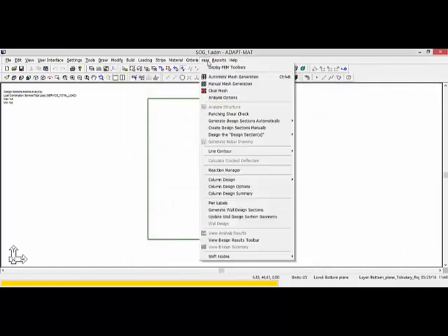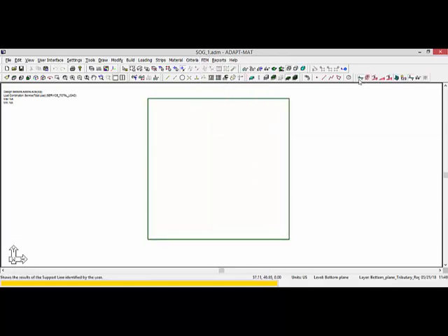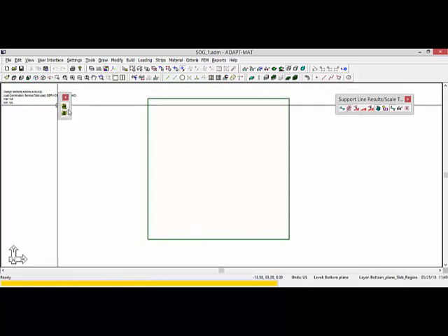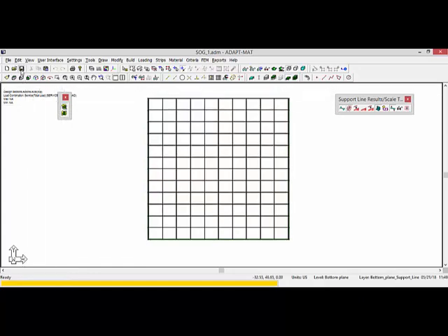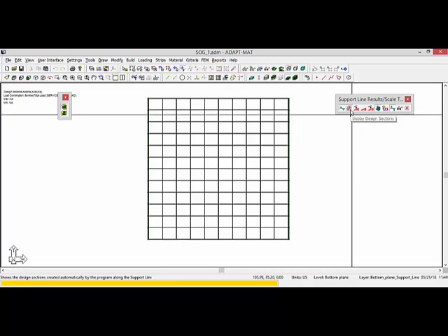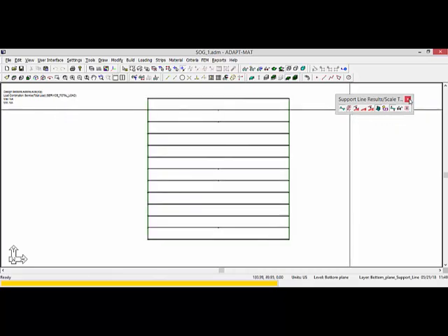I'll go to the FEM View Design Results toolbar, and in the View Design Results toolbar I can see I have this display design sections, and this allows me to toggle between the two directions. Okay, so this is a prerequisite to designing or to determining the load factors for the design cuts.